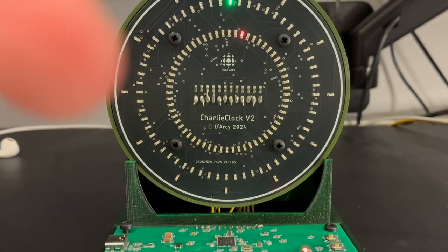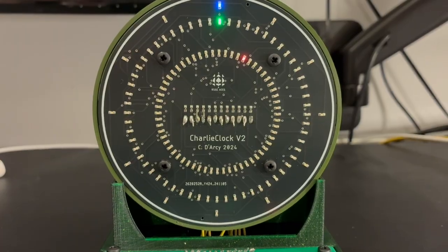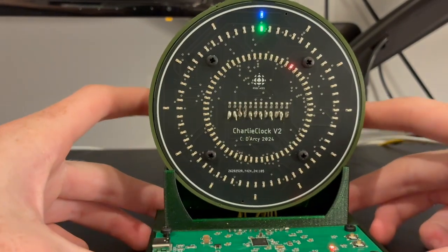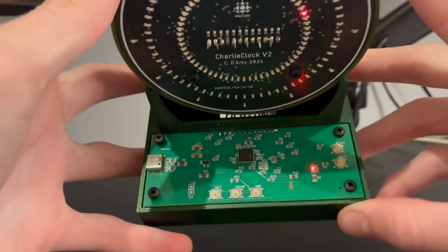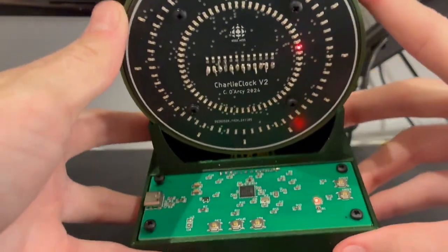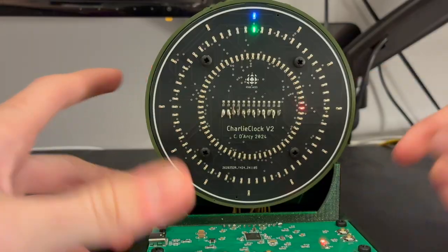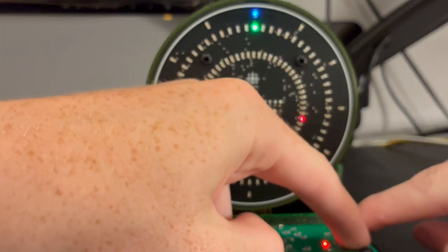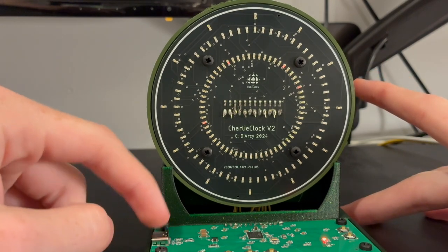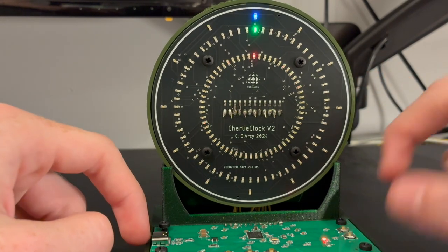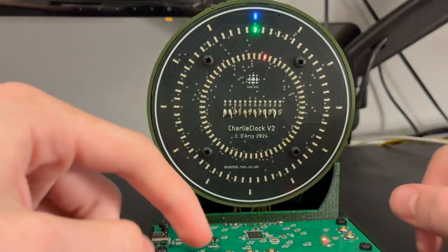The last important part of the circuit is the user interface. See these 5 buttons here. The first 2, right here, are boot and reset. These 2 buttons are used to code the microcontroller. So I press boot and then power cycle or reset, which puts it in DFU mode. It's now available on the USB-C port to code. I press reset again to start it up again.